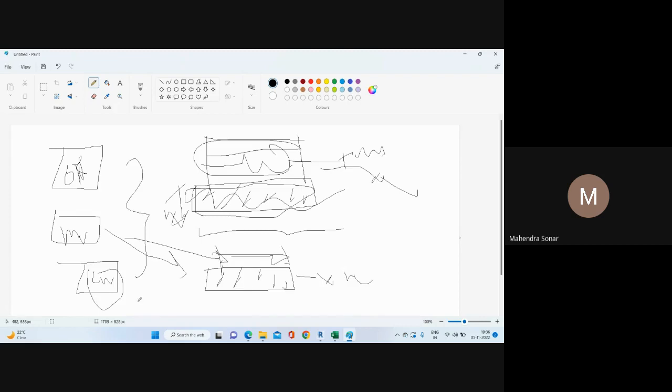So electrical also xrefs both the drawings, or both the models as an xref, and then he can just add his electrical conduits and all other things. For this coordination purpose, you need to set your model at one point, so that if mechanical xrefs your model, it comes at the right location. If electrical xrefs your model, it comes at the right location.